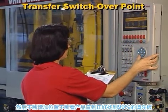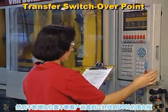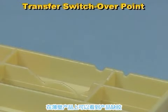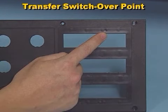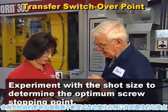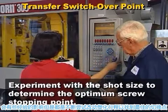Cycle the machine, adjusting the screw stopping point each cycle, until you find the shot volume that fills the mold 95 to 99%. On thinner parts, this point may appear as a very slight short shot. On thicker-walled parts, the part may appear full, but might have pronounced sink marks. Different parts will exhibit different characteristics, but the key is to experiment enough with the shot size to determine this point. This is the optimum screw stopping point.